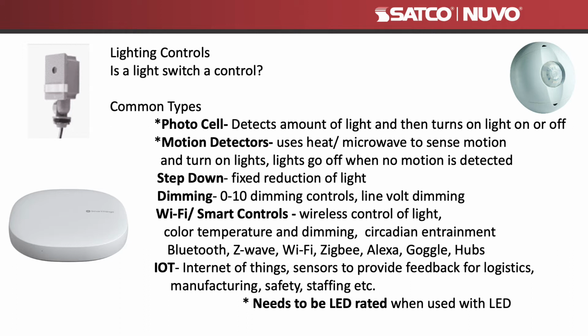Can we look at step-down dimming in that exterior fixture? If we combine a motion sensor with a photocell, well, if there's no motion, the light stays on, but at a lower level. This is also very common in a stairwell. Most of the time, nobody's in a stairwell. So have a small amount of light until someone enters it.